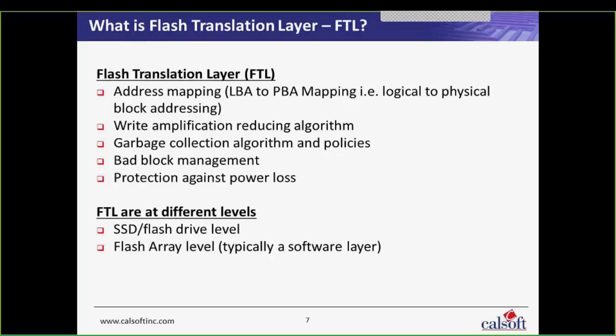So this deals with how garbage collection on FTL will behave, and what the kicking time of the garbage collection engine is, like when it should kick in, and what is the particular time to kick in that particular garbage collection engine, because unnecessary running of the garbage collection engine can impact the performance in a worse way.